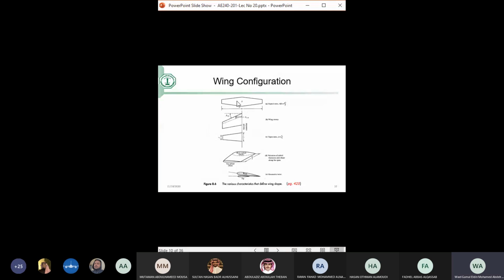Also, are we going to sweep the wing? That means, is there going to be an angle between the leading edge and the normal to the center line of the aircraft? We answered the question of picking 2 airfoils or 1 airfoil, and in this example, we picked 2 airfoils and took the average of both. Remember, we needed a thicker airfoil in the center so that we can retract the landing gear and put the fuel tank, and we took a thinner airfoil toward the tip.